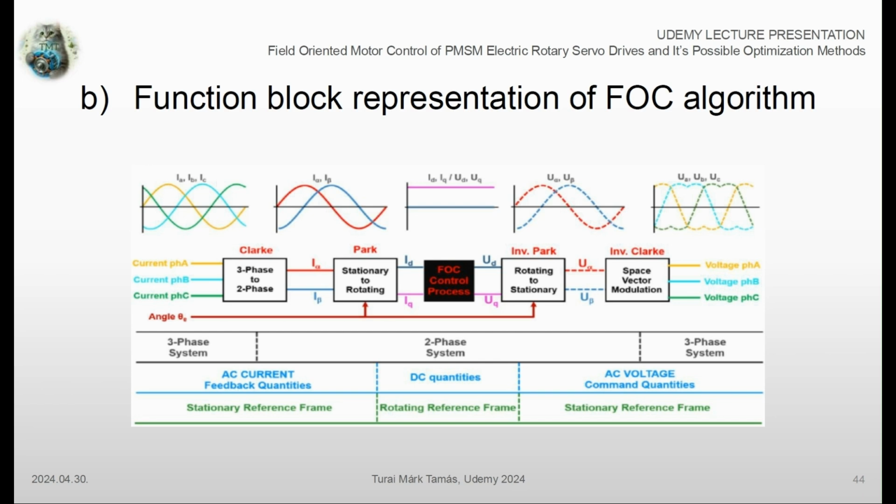To mention the previous example, this scenario would mean that the observer is sitting in the car, which doesn't have a relative motion compared to the observer. In this rotating reference frame, the measured phase currents and other physical quantities such as fluxes and phase voltages can be observed as if they were plain DC quantities. These coordinate transformations from AC to DC quantities are mandatory to ensure the sufficient working behavior of the PI regulators